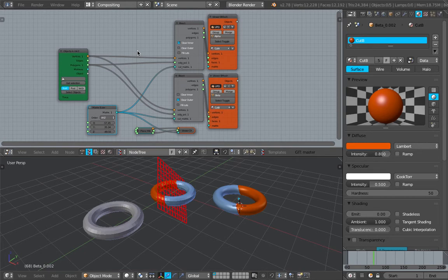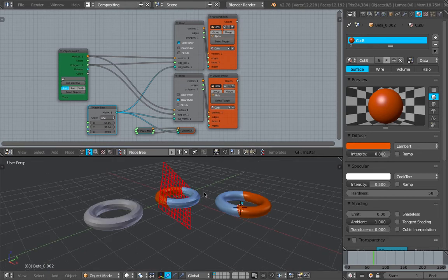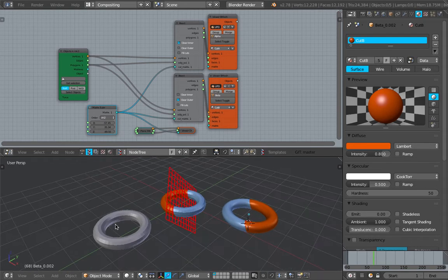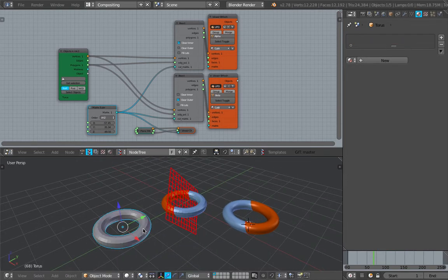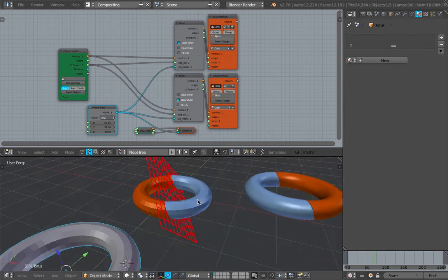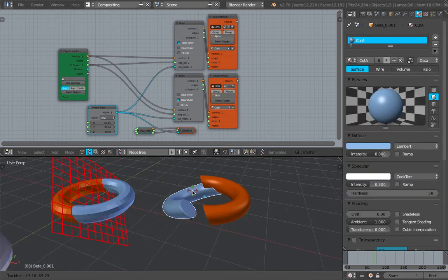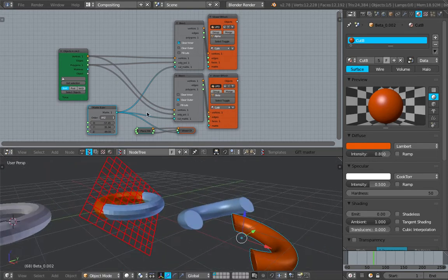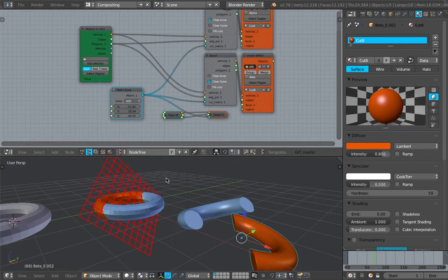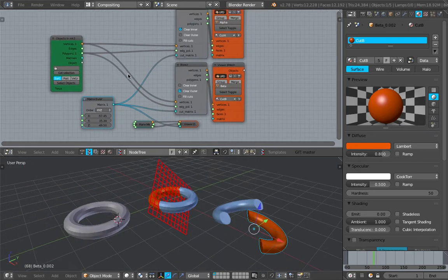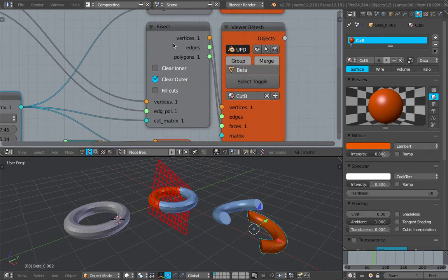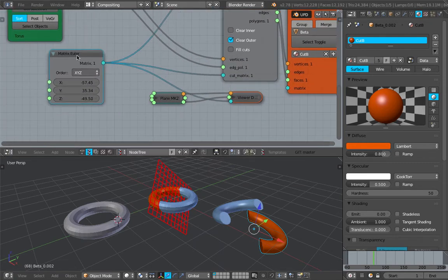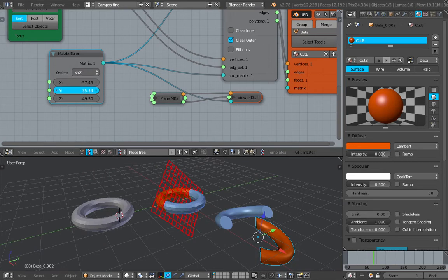This is gonna be a quick, simple, basic video tutorial. So basically, if you have a 3D object and you want to cut it in half, and then give it a different material, so that you can have two nice pieces like this, here is how you can use Sverchok to do this. Even though I think I probably already talked about the bisect node, I haven't talked about how we can use a MATRIX EULER to visualize the cutter. Okay, so let's just get started.